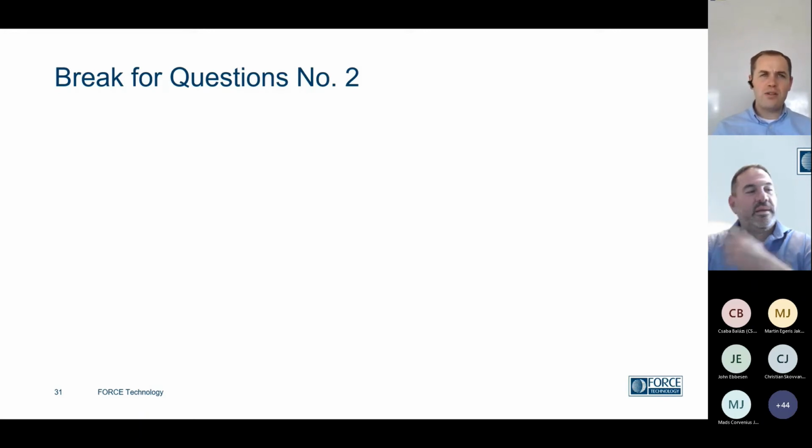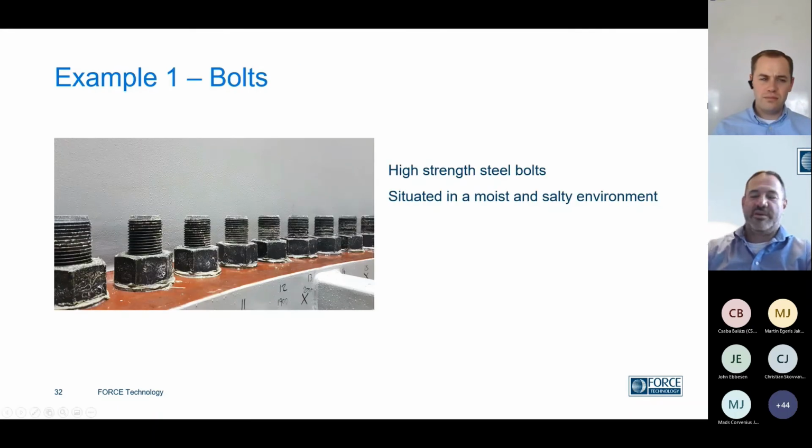And I think in some regards, the point of introducing it here was also just to give the indication, not necessarily that if you're under the endurance limit, you can check mark your fatigue life as okay, but at minimum to introduce this point that there is a change in slope of the fatigue curve, that after you've passed that knee, you have a much shallower slope and a much longer potential fatigue life. Great, thanks, Eric.